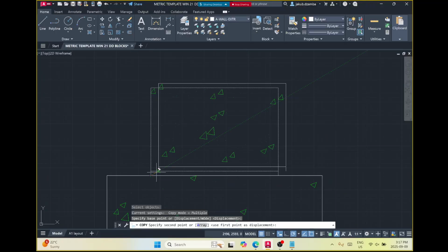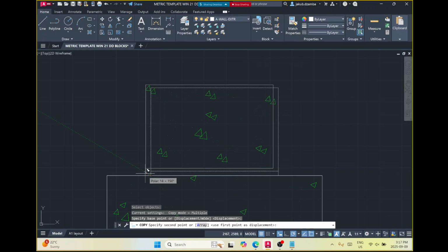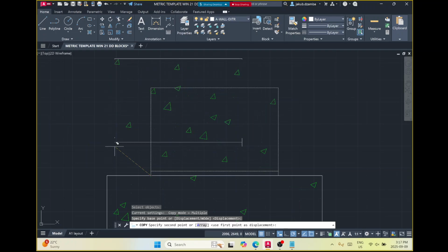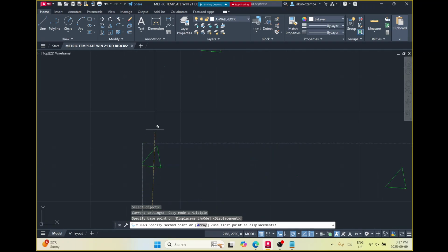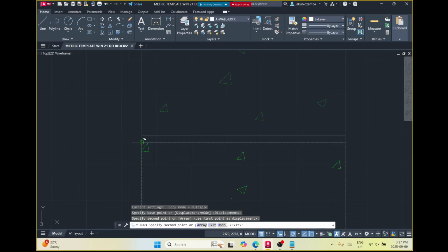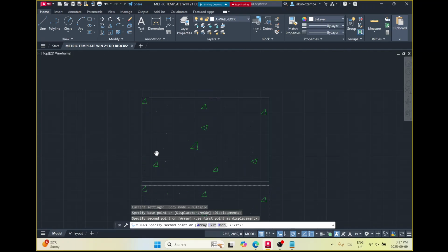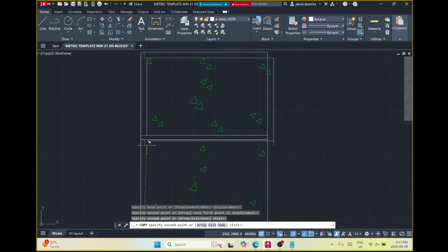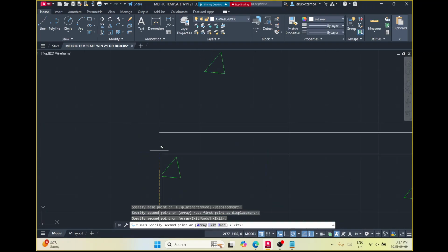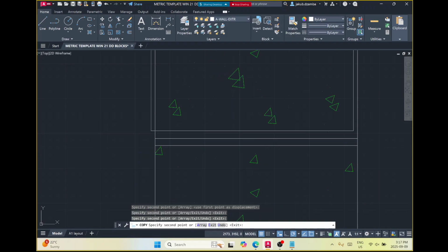And now I'll do it again. So I'll show you where this is going, then I'll repeat the whole process so you can follow along. Now that I have it, I can basically copy this block using that bottom left corner as a handle. And so I'm going to do this leapfrog method. So I'm going to go up, zoom into the top corner of my existing block, and click on it. And then I'm going to zoom out and zoom into the top corner of the new block I made and click on that. And so on and so on. And I can add 12 courses relatively quickly.